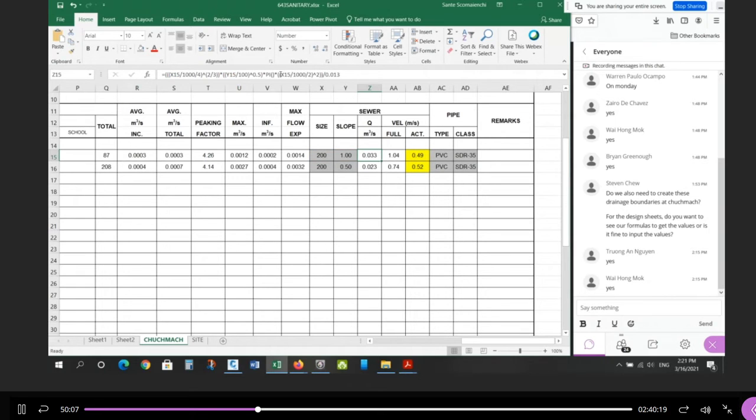Again, the pipe size in millimeters divided by 1,000 so that it's in meters, divide by 2 so that I have the radius, square it, and then multiply by pi. This is how you type in pi on the computer. Equals pi bracket bracket, and that'll give you the value 3.14, with as many decimal places as you like. So that's the code for pi.